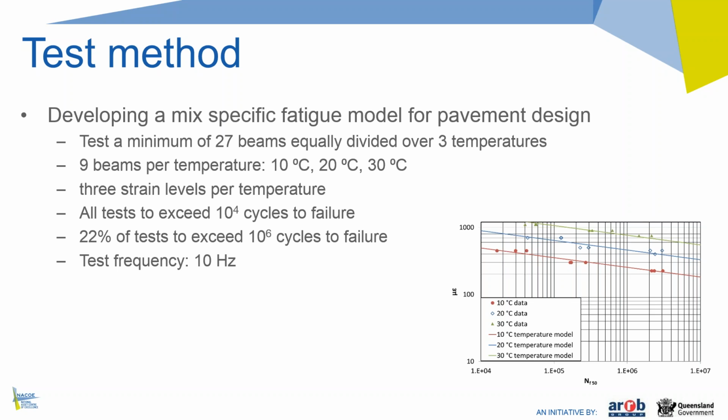So 27 beams and not 3 times 18, is that statistically... We're fitting 27 beams, or 27 results, against a single model, whereas in the other test method we're fitting 18 results against a single model. So statistically we're very confident in the results. If we use 27, we don't necessarily have to test 3 times 18, because the slope of the line remains the same.